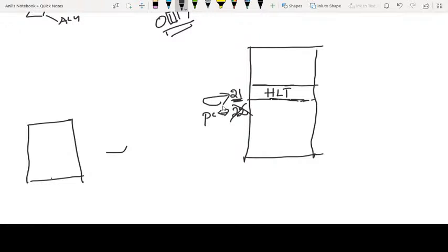For any other instruction, the program counter value is the address of the next instruction, except the halt instruction. Only for the halt instruction, the current instruction address and the program counter value are exactly equal. The program counter value will not be updated for the halt instruction.